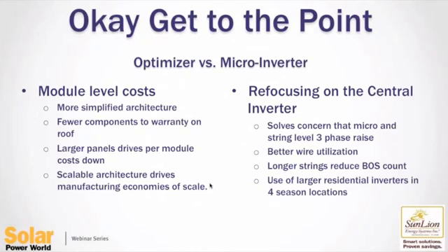Remember, voltage is cheap, amperage is expensive, and so in a system where you're pushing 500 into a 600 volt, or 800-900 into a 1,000 volt system, that wire is being utilized much higher than a microinverter system where the long trunk runs are only 240 volts on a 600 volt wire. There's a lot of extra headroom in that wire that's wasted. What we've also seen on the longer strings for the smart modules is we've been able to remove components. I was talking about some of the NFPA requirements, especially when it comes to disconnects at fuse combining points.